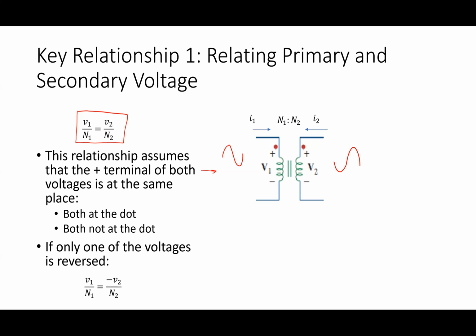So if I had two coils on top of each other and both the voltages lined up with each other, so they both looked like this, if I then switched the leads on my oscilloscope, I would see the polarity of the voltage flip 180 degrees. In other words, if I put a voltage source plus to minus like this, and I measure plus to minus like this, then I'll see that. If I measured plus to minus like this, then this guy would flip over.